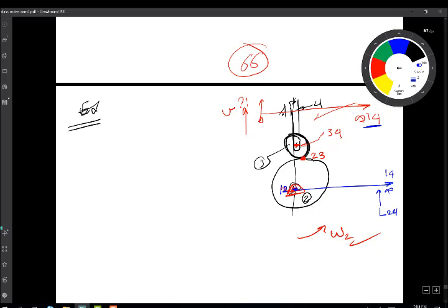I can see it here on my roller. So the center of the roller is 3, 4, and the point of contact is 2, 4. So if I connect them together, I get another locus for 2, 4, because 3 is a common number. So if I connect them together like that, those two will give me another locus for 2, 4. So now I have two loci for 2, 4, this horizontal one and this one at an angle. They intersect at a point. This has to be my point 2, 4.